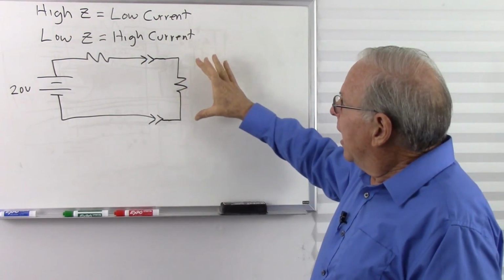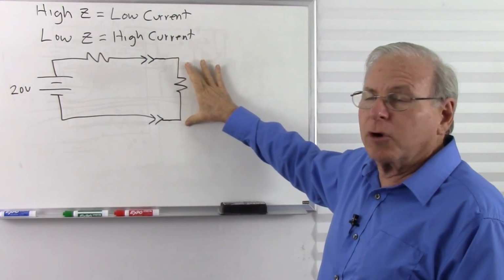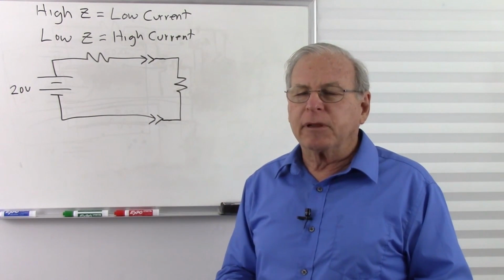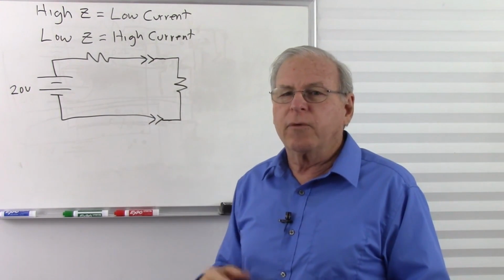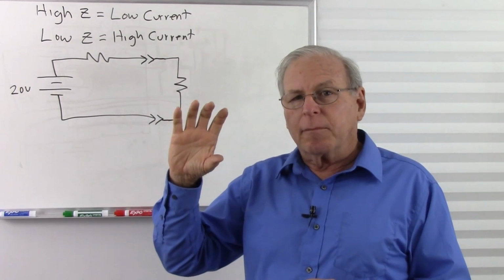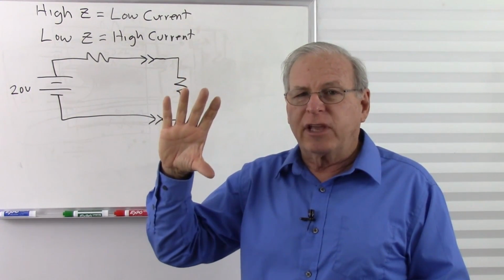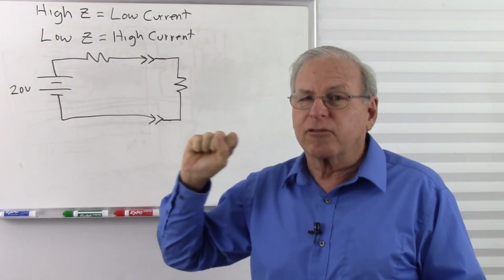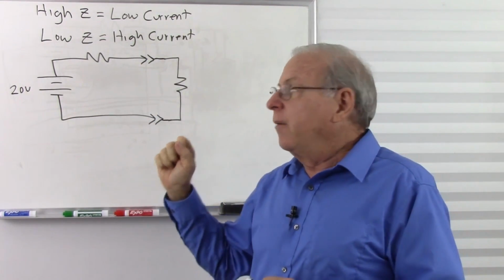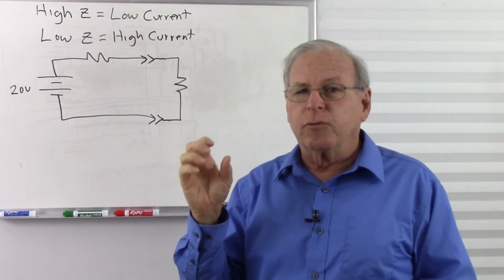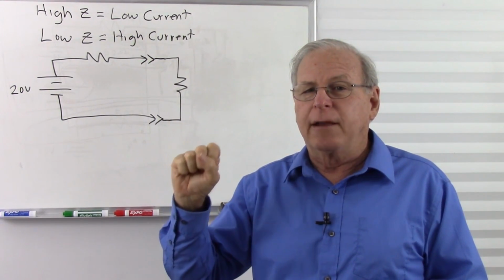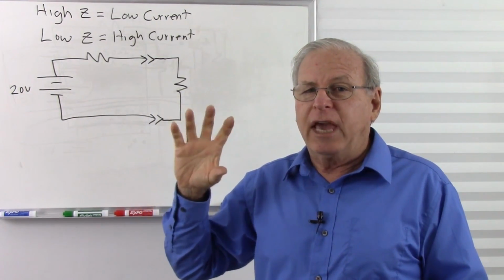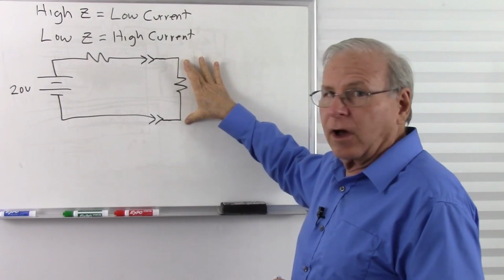Now let's say I have a situation where I want to get the maximum current across my load. This is desirable in a couple of places I can think of off the top of my head. For one, radio transmitters. You want to develop the most power you can across the antenna to transfer as much energy into the luminiferous ether and create the strongest radio waves you can. And when it comes to audio amplifiers, you want to deliver the most power to the speaker you can because you want that power turned into sound waves. And so in both cases, you want to develop the maximum power on the output.